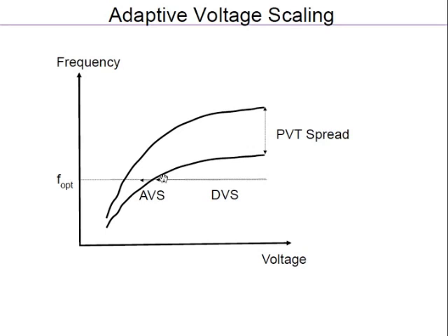Basically what I will do is put in some little ring oscillators, as we discussed in the last class. Ring oscillators are essentially a chain of an odd number of inverters, where the output is connected back to the input, so it will oscillate. You will measure the frequency of the oscillation, and you will get a sense for which curve you are in. Are you in this curve, or this curve, or some intermediate curve? Based on that you use the right value in the table. Maybe you have multiple tables, and then you use the right table for that particular chip.